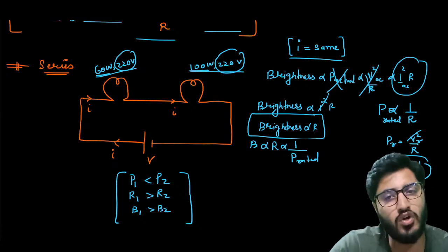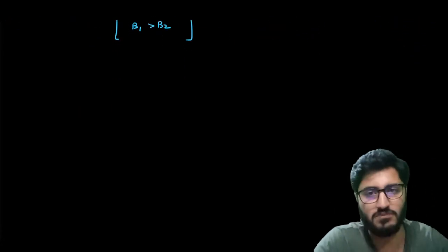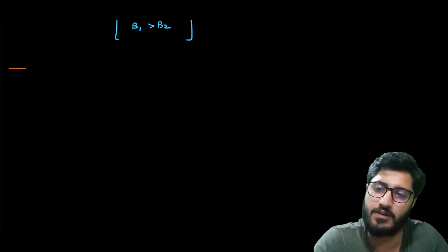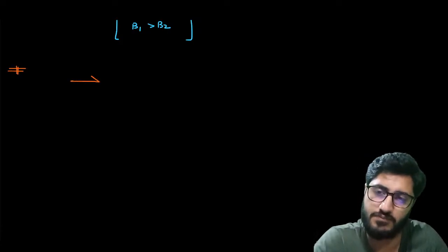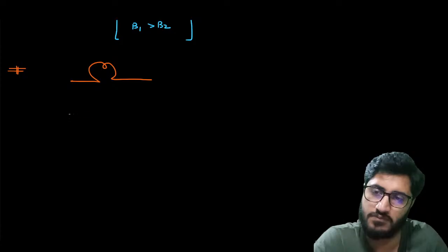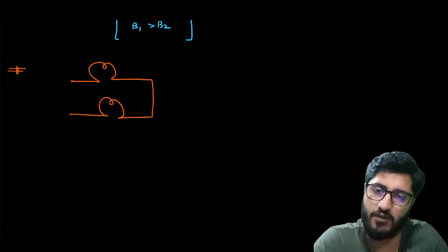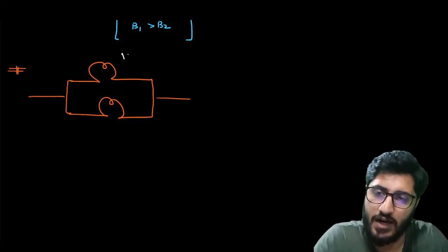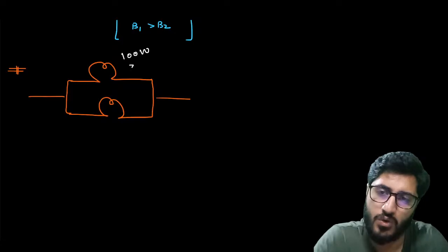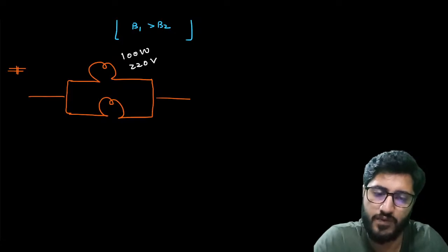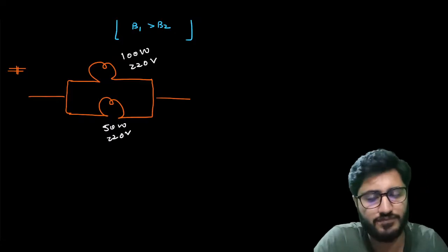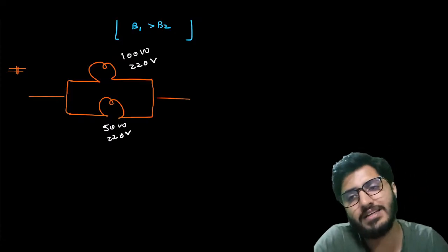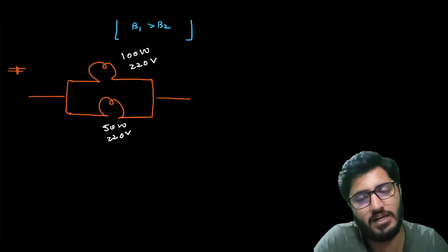Now, sir, if we are talking about the parallel one, look now. If we have parallel, this one is 100 watt, 220 volt, 50 watt, 220 volt. Look here, I guess here the voltage will be the same. In parallel, V will be the same.